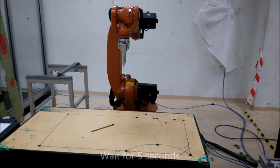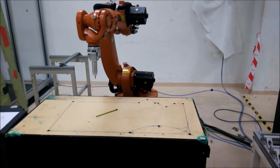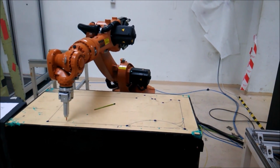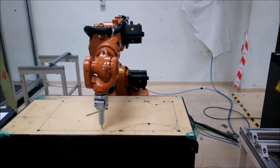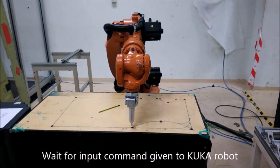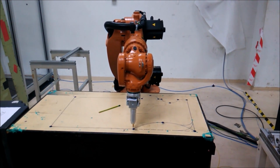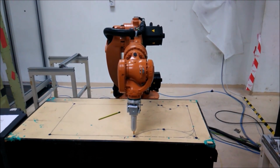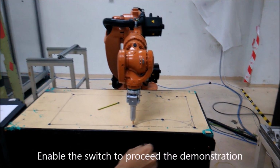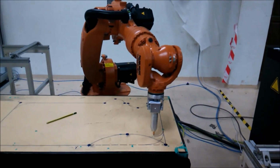As you can see, now it's a wait logic command, which is going to wait for 5 seconds before it moves to the next point. So now at this point, we already set a logic command wait for, which means that I need an input, an input 11, to enable it before we can proceed to the next move, which is I need to switch on the switch over here. Now it continues its movement.